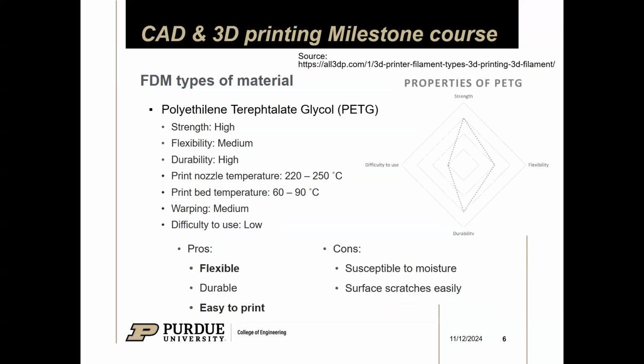But yeah, the next material is PETG. It used to be my favorite material before I started printing in ABS. The only reason why I like ABS more is just because I can print with an enclosure now. But I personally tend to favor PETG over PLA, mainly for its temperature resistance. So it's kind of in the middle between ABS and PLA in that regard.